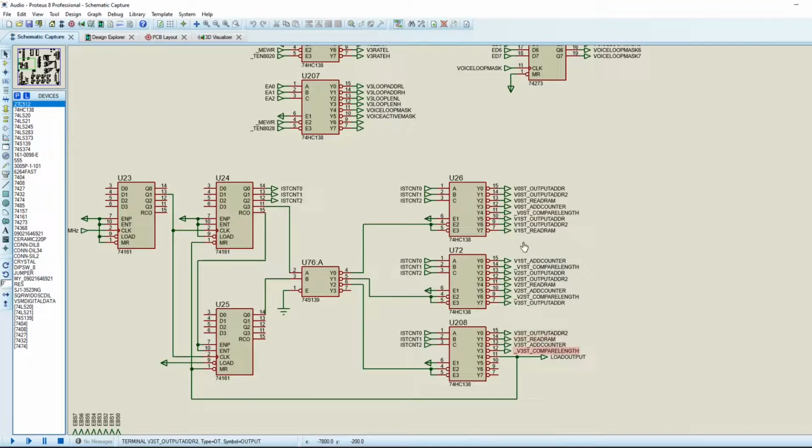We actually have 20 states because this is an asynchronous clear going into the 74 161s. So what this means is that in real terms, the first state here is about 50 nanoseconds or so shorter than all of the other states. But to be honest, we are talking in the region of 2000 nanoseconds for each of these state transitions. So we're really not too worried. You know, this is audio hardware, and audio hardware doesn't have to run as fast as the video hardware does, thankfully.